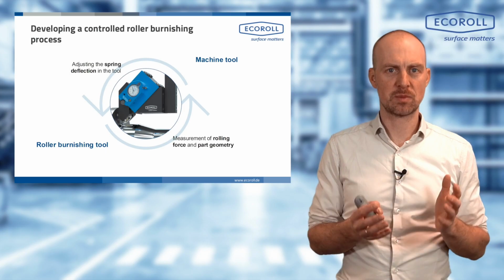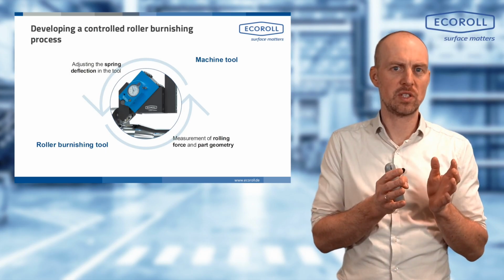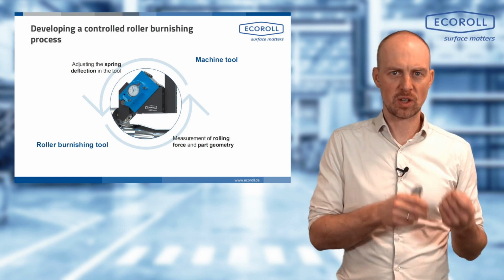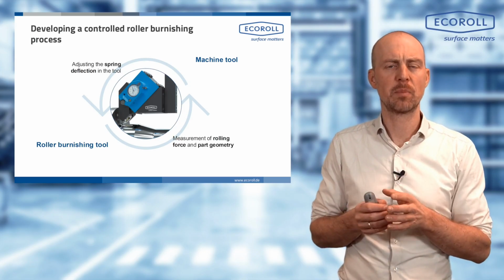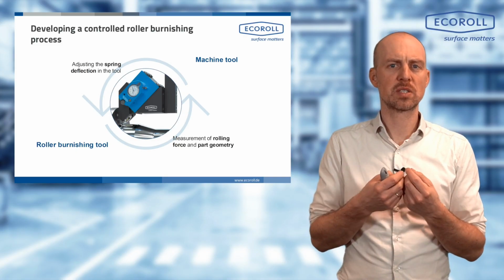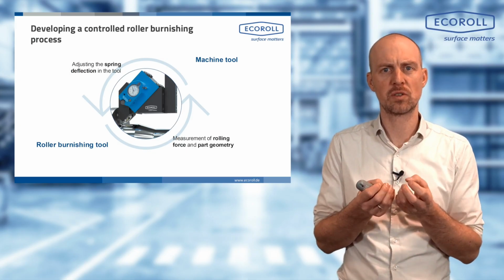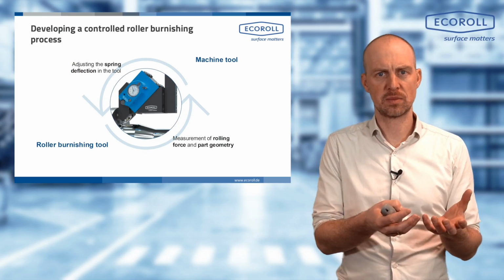What we cannot measure in this process, however, is whether there are any deviations beforehand. Because for the residual stress and also for the strain hardening, the rolling force is not actually the decisive factor, but it was basically also pushed relatively strongly by the University of Bremen by the Leibniz IWT. The so-called process signatures. Process signatures are internal load states within the near surface area that ensure that a specific near surface area state is created.